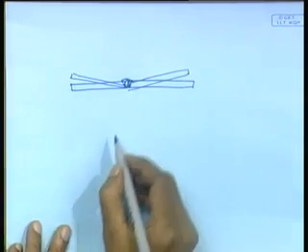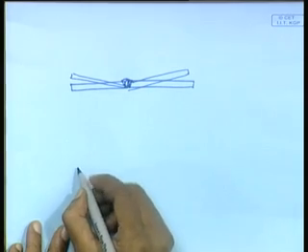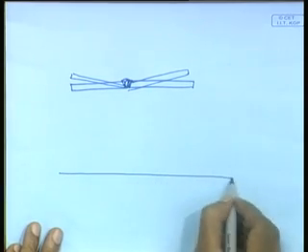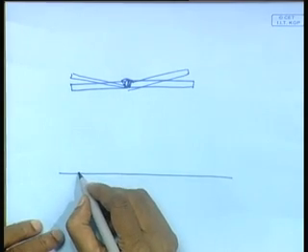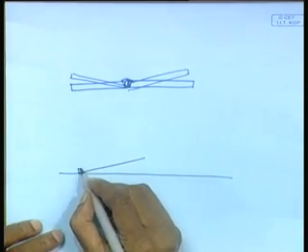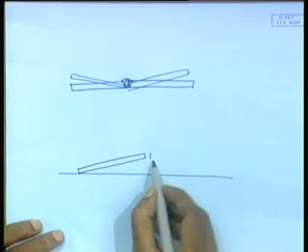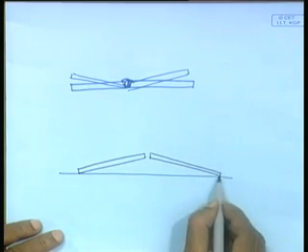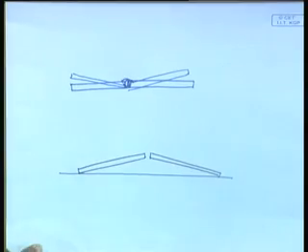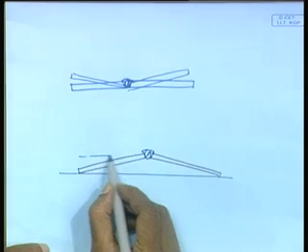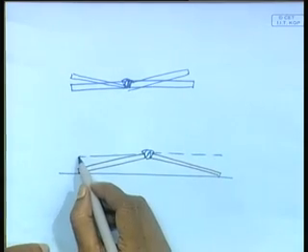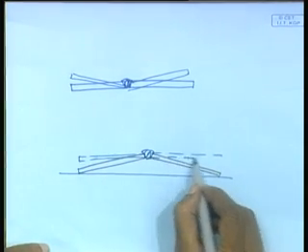So, if I preset it just the opposite way, that means I preset the plates in the opposite way and then weld it, then what will happen is it will lift up and become straight. That is what presetting is. And after the welding is done, then it becomes straight.